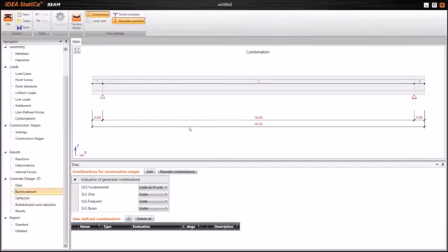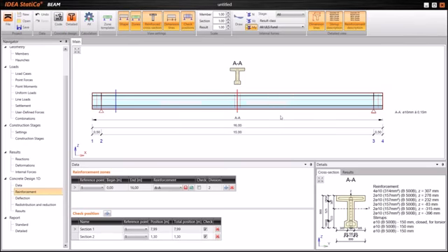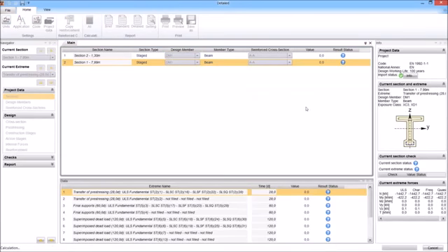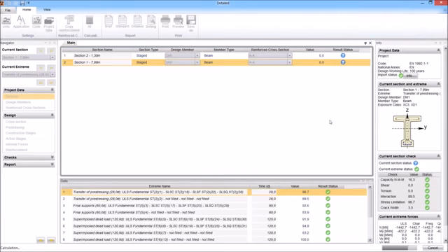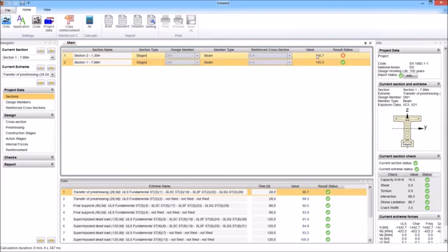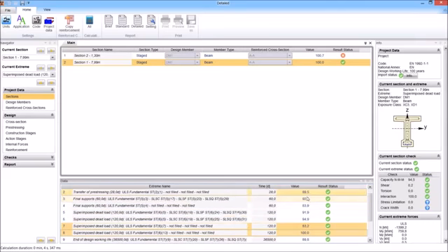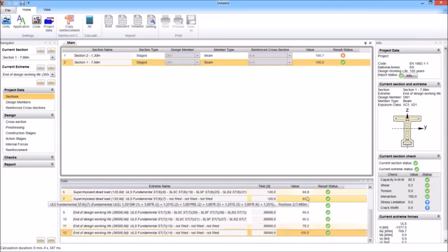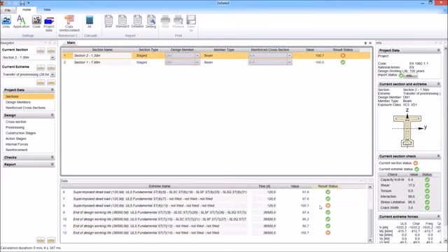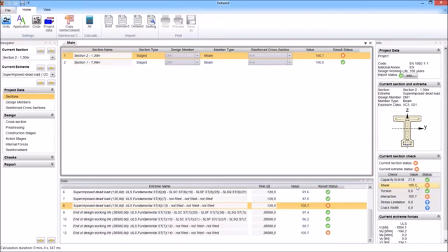Now we go to reinforcement, and again detailed. I run it again, and we see that it will be much better. This is at midspan, it is even satisfactory, and above, and we can also see which one was. You see, it is 94%. We can go through all the checks. We see what the capacity is, and the biggest was 94.5, so it improved significantly. And this shear still needs a little bit more.